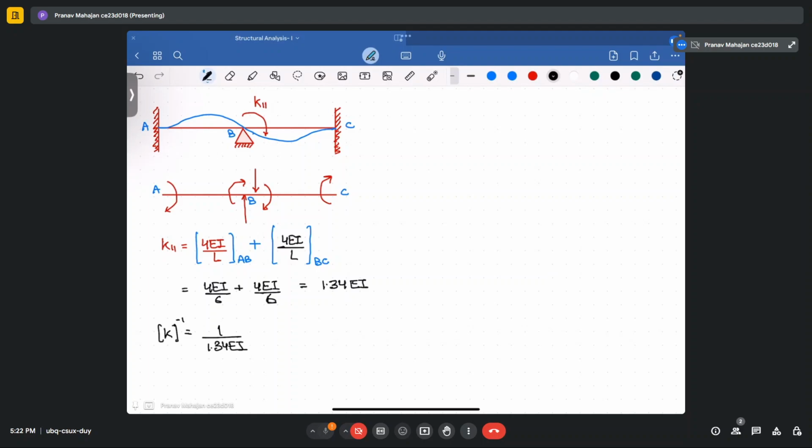So now for the calculation of the structure load vector, you need to determine the end forces that are there in the member. So let's divide the whole beam into fixed beams. So first, due to the simply supported load that is provided over the AB length.